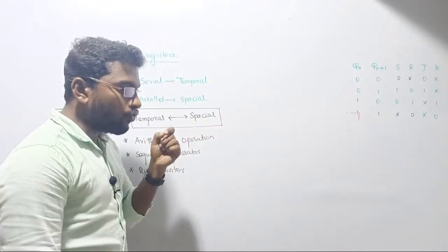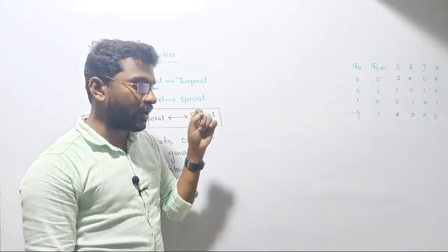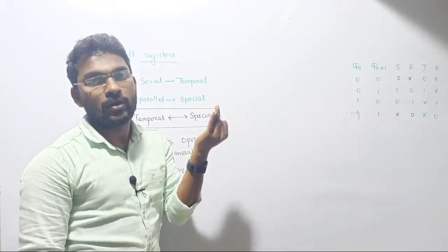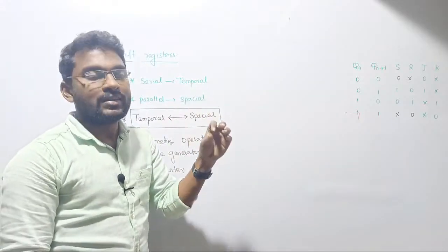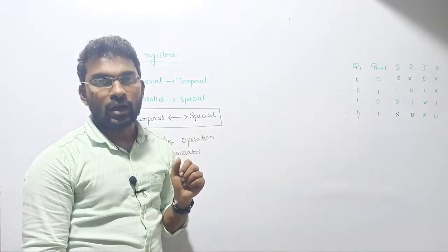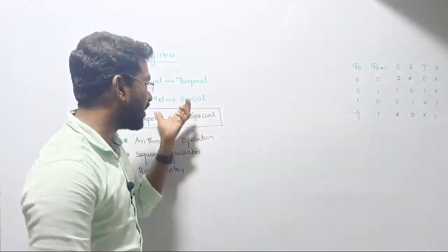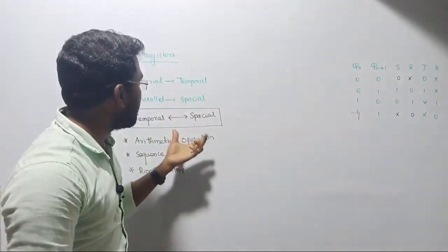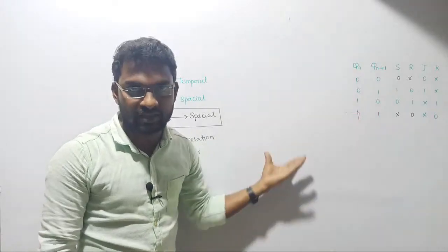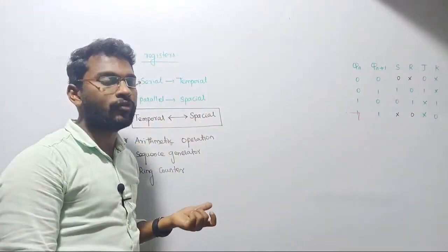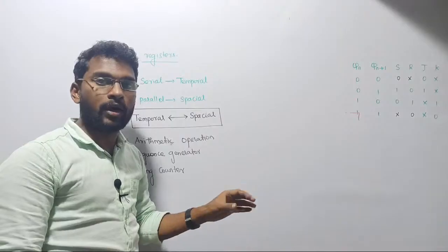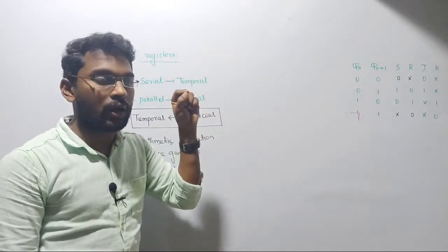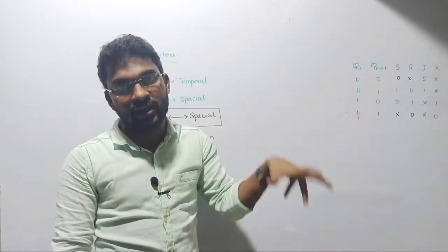But if you are trying to implement this circuit with other flip-flops like SR, JK or T flip-flop, there might be a need for some logic gates. Otherwise we cannot design the circuit simply. You can perform the same operations that we perform with the D flip-flop using other flip-flops, but you are also required to consider some logic gates along with the flip-flop.